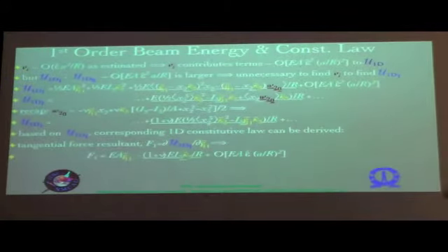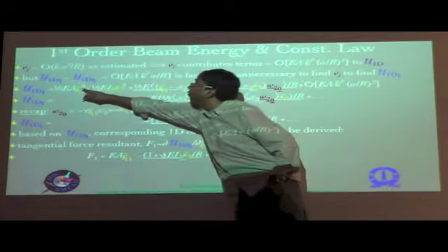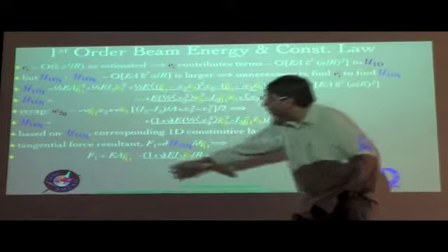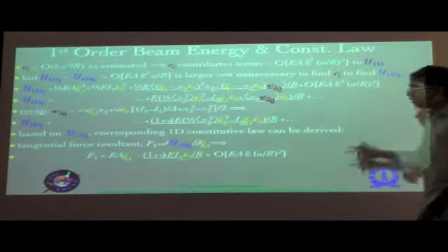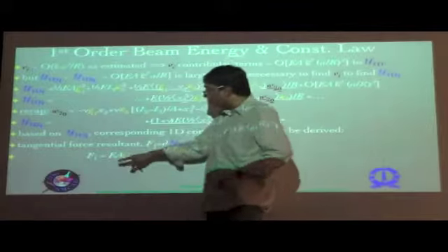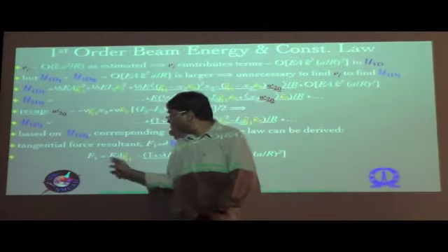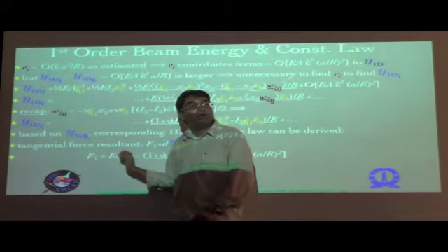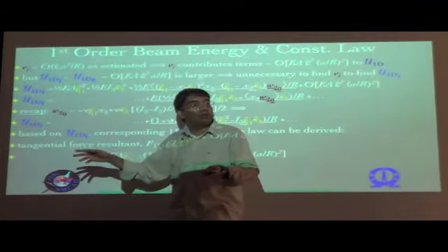So if we actually substitute for that U1D, of course taking into account these two terms as well, and take that derivative, then you see that F1 is given by this. The first term is eerily familiar. Your axial force resultant is given by the axial stiffness times the axial strain that you are already familiar with, and that's what you got in the zeroth order approximation.